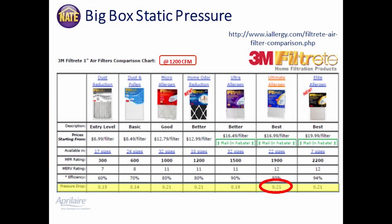So let's take a look at some 1-inch filters. These are very popular filters. This information comes from their spec sheets. We're looking at a variety of different filters. Let's focus on the ultimate allergen. At 1200 CFM, it's got a static pressure of 0.21 inches water column. That's its initial static pressure.